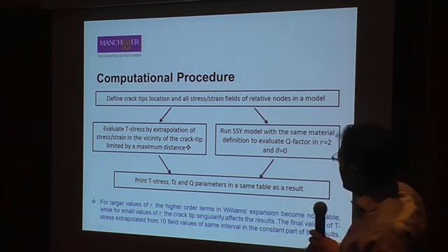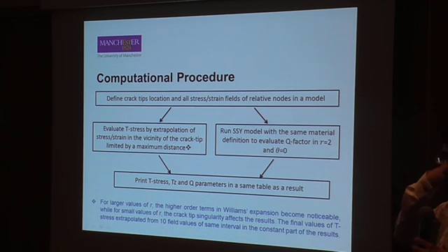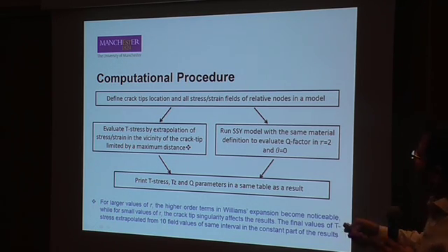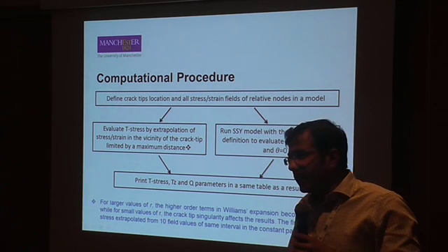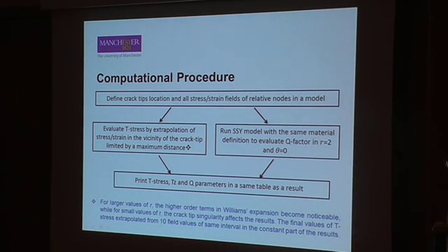I will give you my algorithm to calculate these two parameters. The user only has to define the crack tip. I calculated the location of the crack tip and all stress and strain fields at all relevant nodes. If there is a node, we can pick up this node. If there is not any node, I projected the stress onto the specific direction, our preferred direction. Then stress can be interpolated and extrapolated from a specific distance, because this distance r is very important.